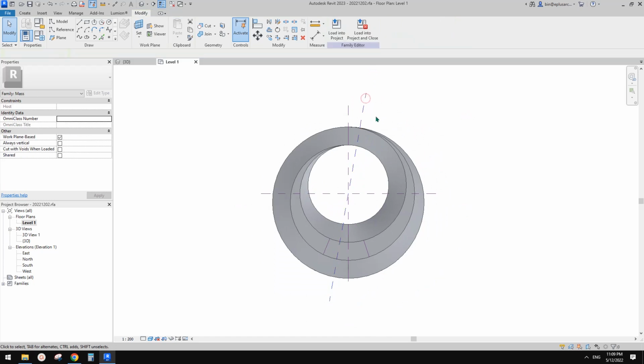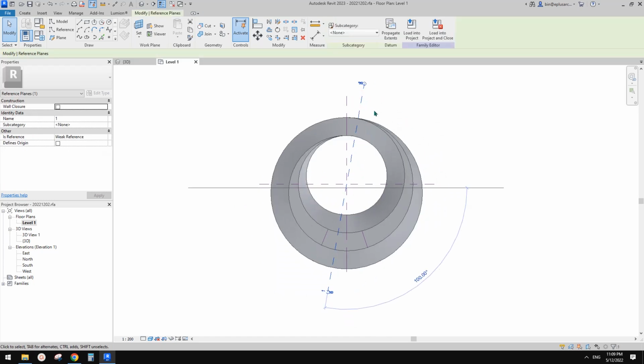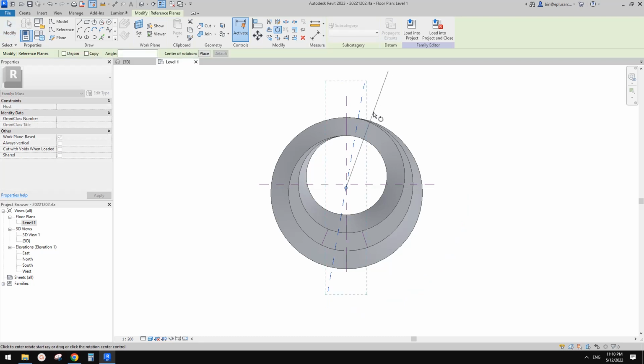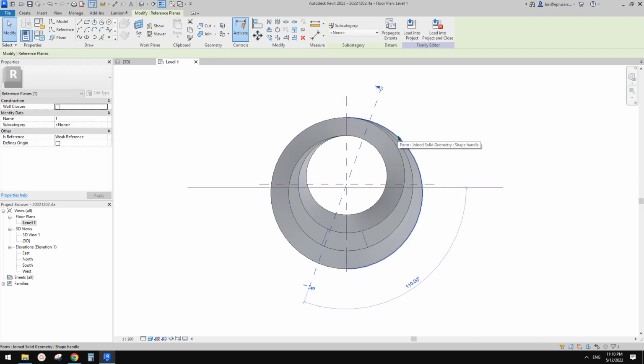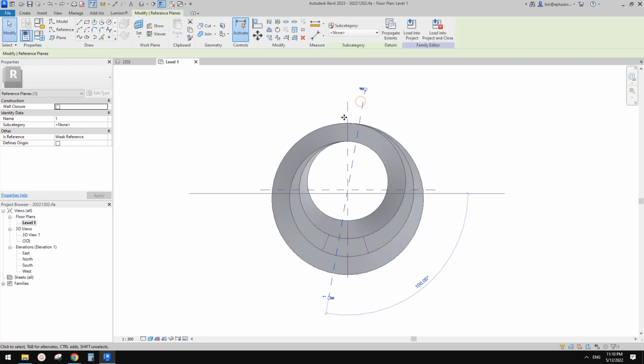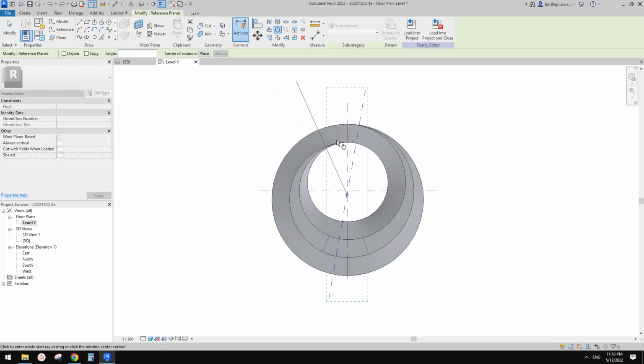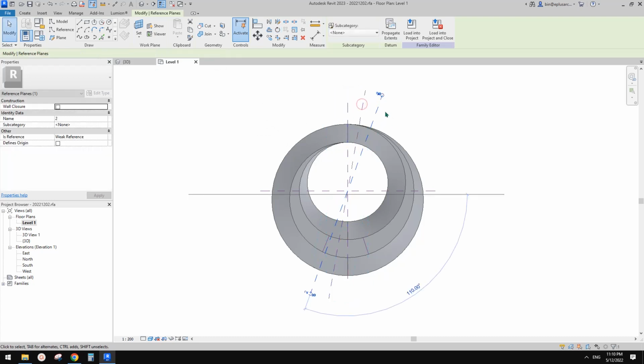So I'll also maximize 3D extend. Okay, so that's good. Now I'm going to, what should I do? Rotate, space, pick the midpoint, another 10 degree. Ooh, Control Z. I forgot to tick the copy. So let's do it again. RO space, center, copy here to here. So we have another one.